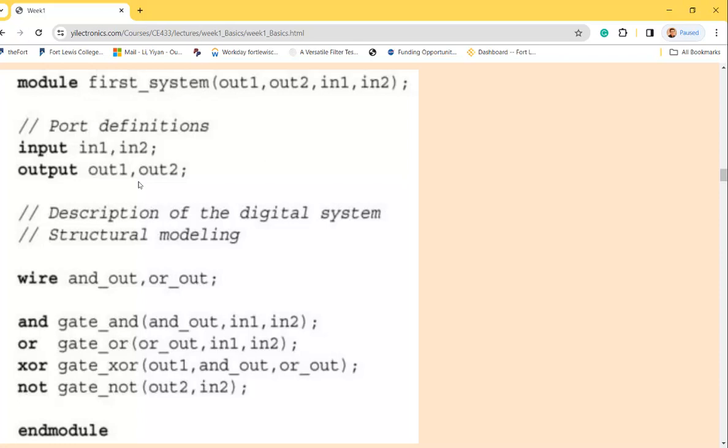You'll be able to know when to use reg and when to use wire later on. An easier way to understand this is that a register data type is usually something that can store data, so it's usually a flip-flop or a register, like a D flip-flop. But a wire is just a single wire. It's a piece of metal wire, which cannot store data on it, right? It's just a conductor.